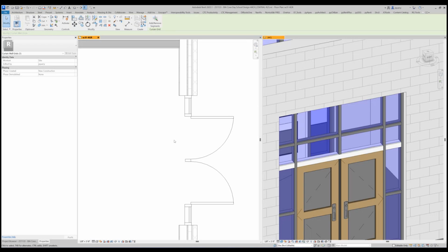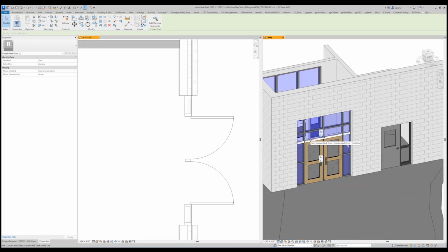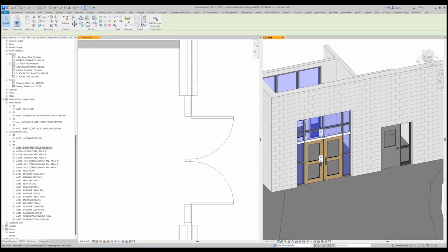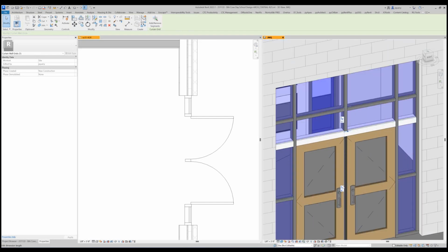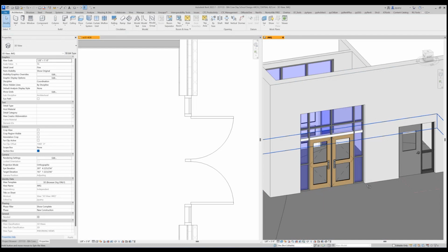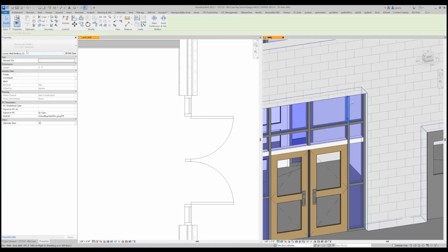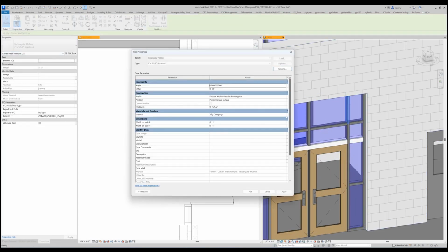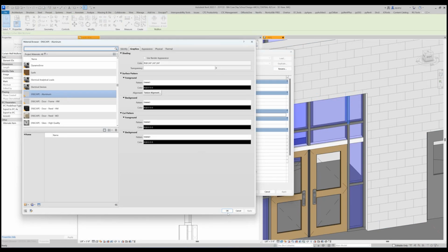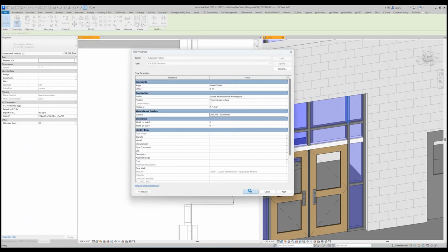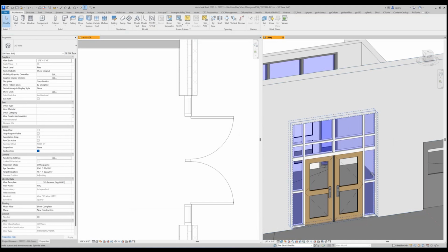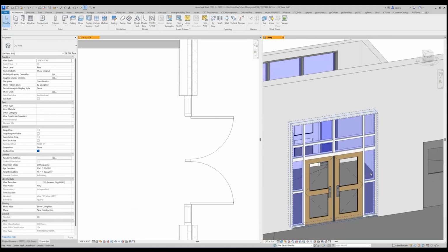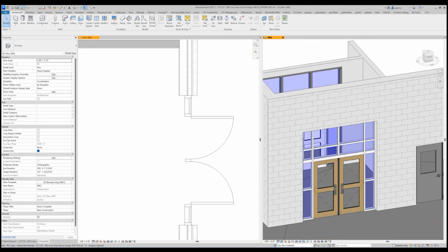And I'll show you another trick here in a second, but let's get this thing to where it should be. Right now it's 7.1. What do you think it's got to go to? 7.2. There you go. This is an easy one for height. It's the width ones that get crazy, and I'll show you that in a second. Now you'll notice that these guys by default do not have a material, so I'm going to go ahead and give that the Enscape aluminum, so that way they're all white. Cool. We can always change that later. All right, so we've got that going for us. I'm going to go ahead and save this so I don't lose it.